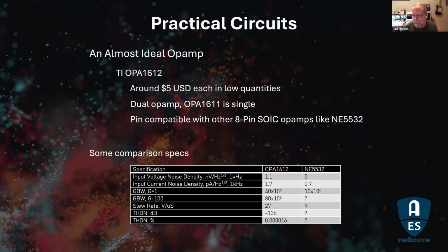There's a lot you could choose from. In a lot of cases, you could just do a swap with these and get better performance, but not always, because if it's a low source impedance, this is an excellent op amp. But if it's a high impedance source that you're amplifying, this is probably not a very good one for that.